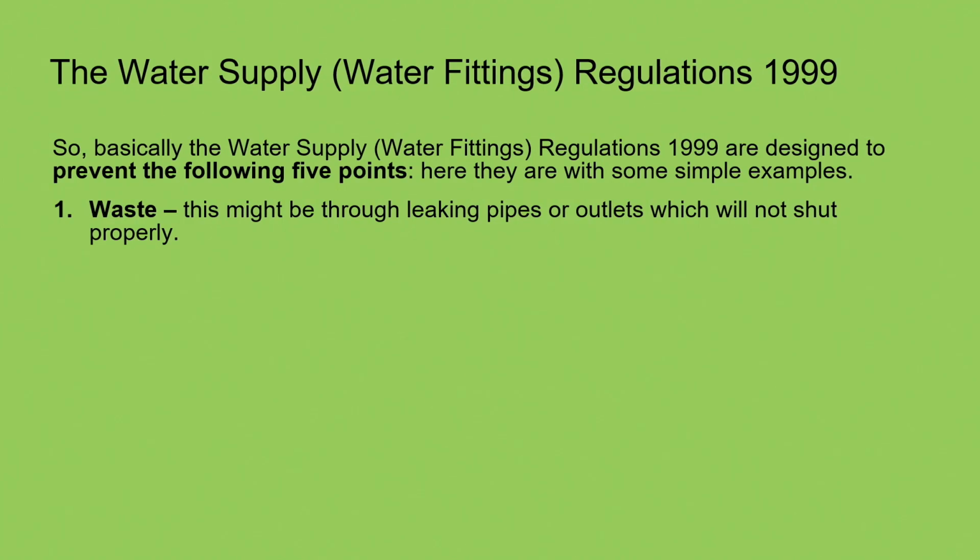One of the jobs I used to like doing was replacing mains going into the property. I used to enjoy that part, digging holes, finding the old mains, finding if I can repair the leak. If I can't repair the leak, I would put new mains in. That way it would stop the waste, and the water undertaker was happy and the customer was happy. So waste is an important one. We do lose a lot of water due to leaks underground.